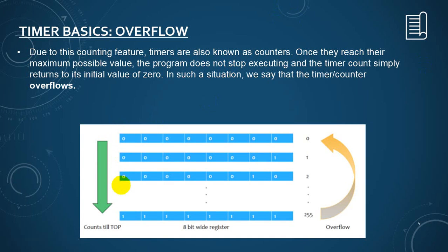Then it will set a bit in a register. By checking those bits, we know that one count has been made. Okay, so clear the counter on compare. After 200 again it will go back to 0. So there are different ways we can do the counting.